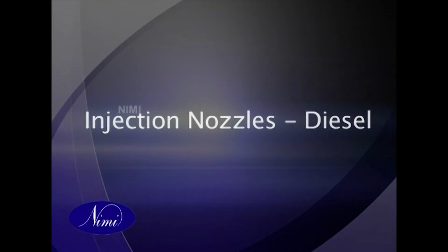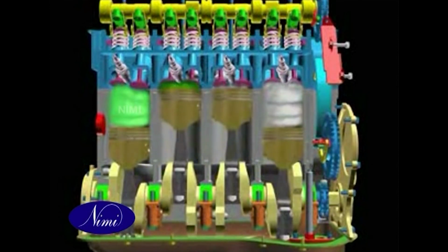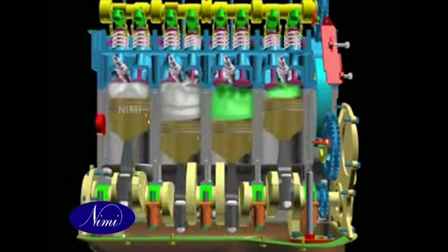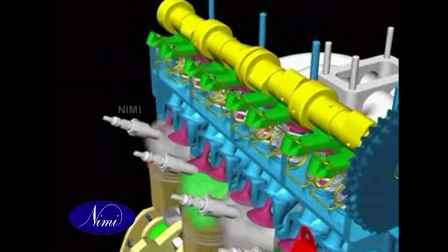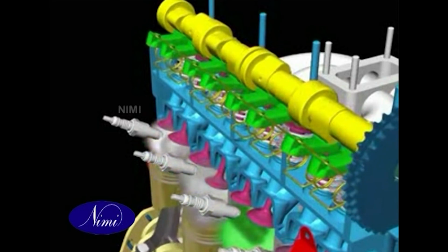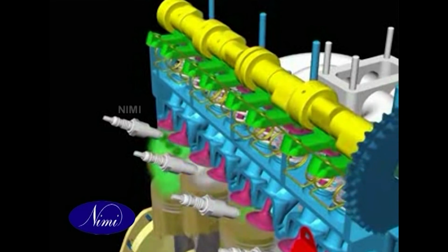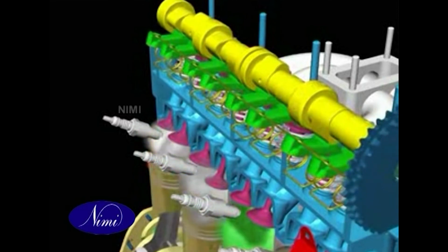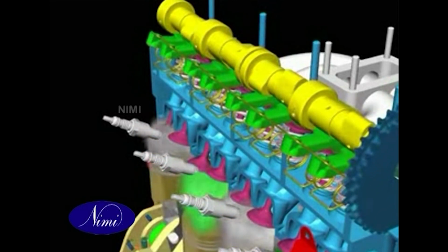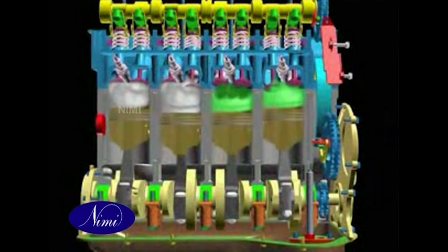Injection nozzles, diesel. Injection nozzles for diesel engines feed the fuel into the combustion chamber, vaporize the fuel, shape the injection process and seal the combustion chamber. They consist of the nozzle body or nozzle holder assembly and the nozzle needle. The nozzle holder assembly provides pressure-proof mounting in the cylinder head and contains 1 or 2 pressure springs, as well as other components for adjusting the injection pressure.